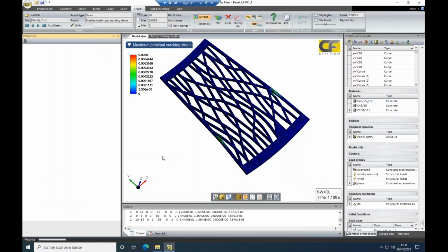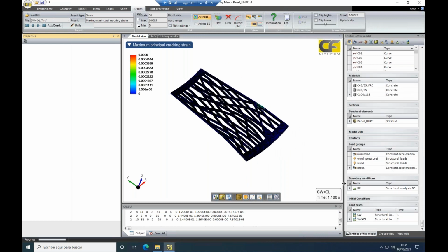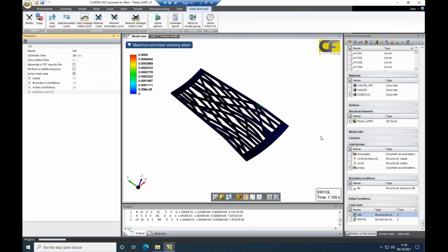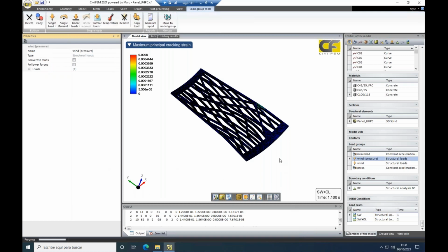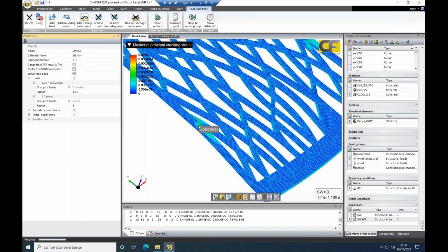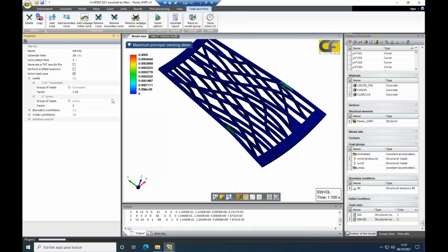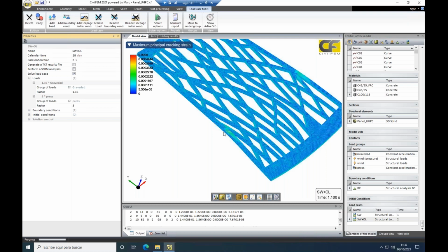Well, just opening model, and you can see here we have 45 degrees. We have created a first cell weight configuration. Then we have added wind loads, and the next step is adding here for this pressure or this wind loads a safety factor. Example, increasing 3 times the wind loads, or also the gravity could be increased 3.5. So these are factors that are applied to the loads, and then we can solve until the model is broken and the software stops converging. So we can obtain a load safety factor, just obtaining the maximum factor where the model converges, and it means it will have the collapse of this roof.